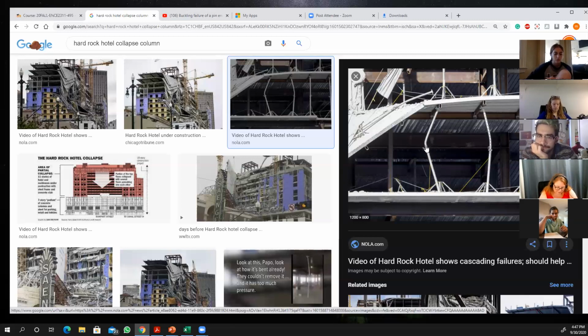But you don't see that it yielded. Yielding is different from buckling. So you have to calculate the yielding and the maximum compressive strength if it's reinforced concrete, and see which one fails first. Is it going to buckle first, or is it going to crush under the compression load, or is it going to yield if it's steel? When I say yield, it's going to be deformed permanently.